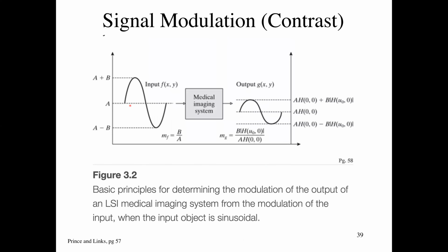And that is, I have an input of a sine wave, it goes into my imaging system. What comes out? Does that frequency get attenuated? And we ask that question for all possible input frequencies, right? So the minimum input frequency is if this sine wave is a constant, it's just a DC value, how bright is the whole field and there's no change on the field, versus a sine wave of a specific frequency. And then we'll look at a sine wave of a higher frequency, higher frequency, higher frequency.